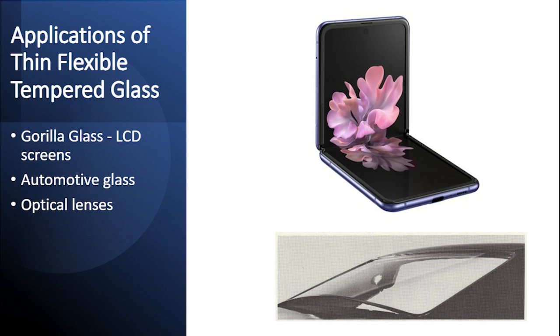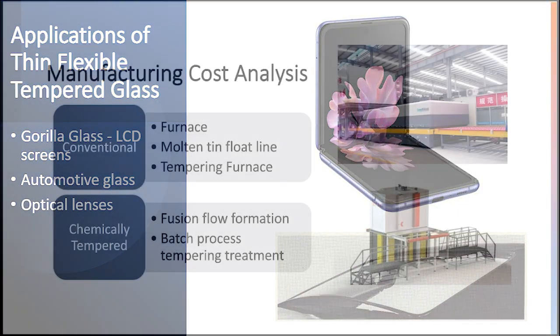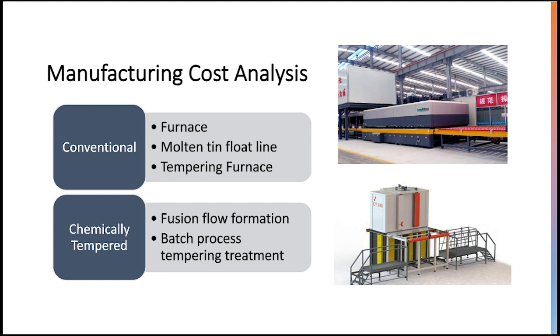Gorilla Glass, a product of Corning, is a popular tempered glass used for cell phones. Before cell phones, however, Corning was focused on the use of flexible tempered glass for automotive windows. These glass products could flex or hinge and allow for easy removal in convertibles. Today, thin flexible tempered glass is used in many of the same applications where conventional heat tempered glass was originally used. For instance, curved glass panels can now be made with thin flexible glass as opposed to forming glass before heat tempering it.